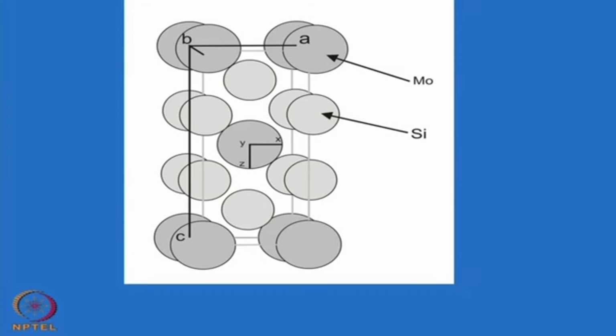This is one material. In fact, like silicon carbide is a semiconducting material. Some form of silicon carbide has a good semiconducting property, and in fact it has been used as a high temperature semiconductor. So, the electrical properties of many of these non-oxide ceramics are quite interesting, and in that context molybdenum disilicide has a fairly large conductivity, but not like fully conductors like metallic conductors, but it has some resistance but fairly conducting.